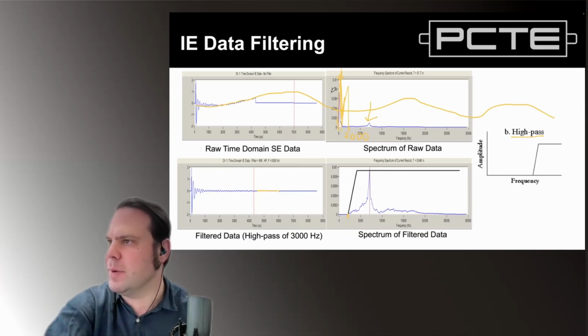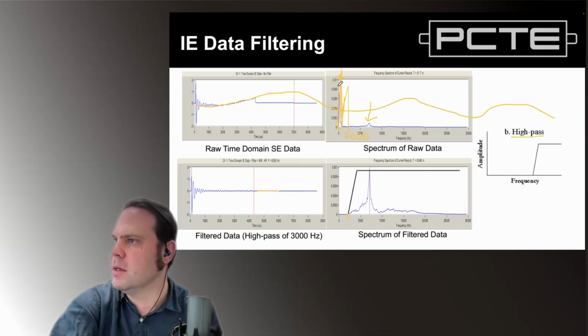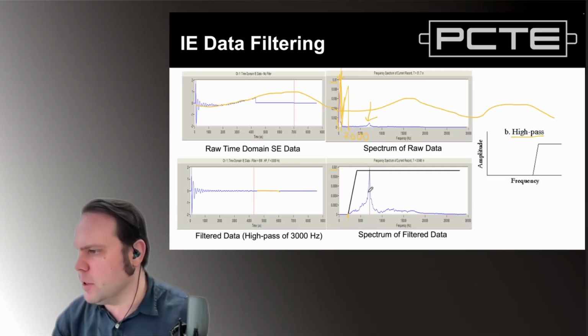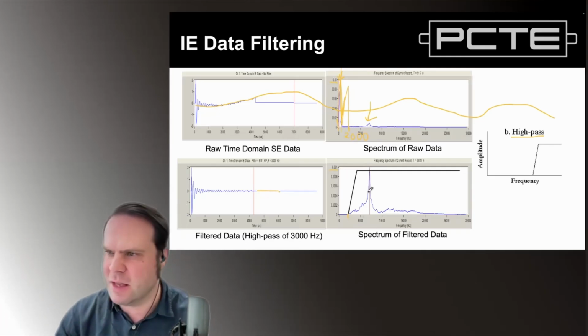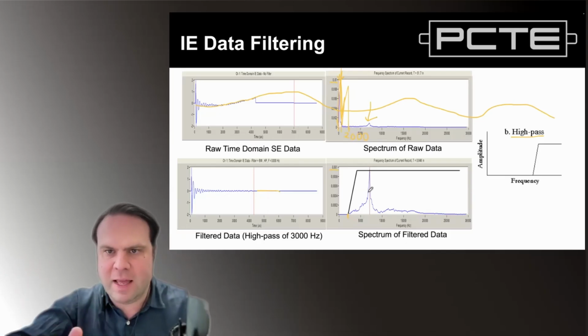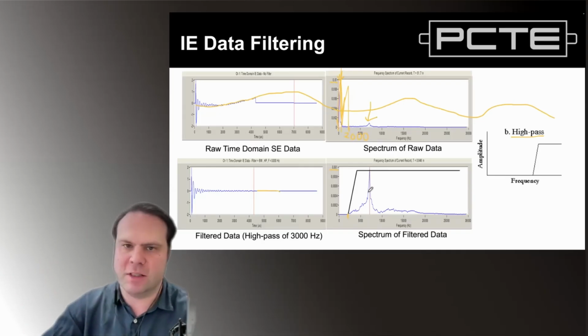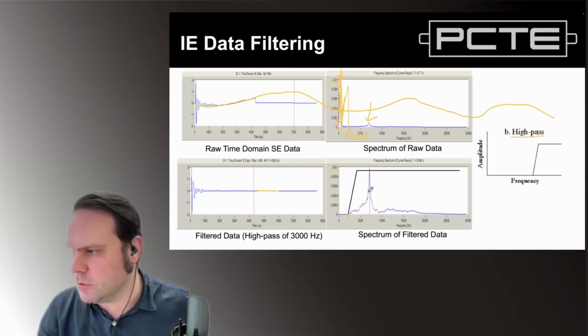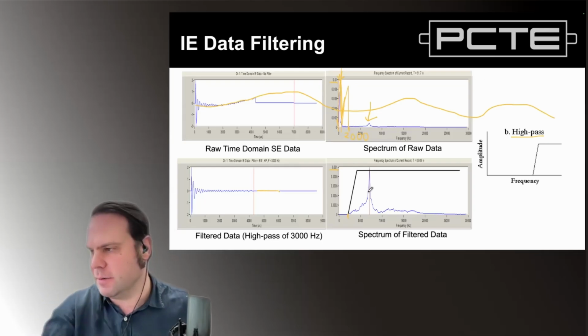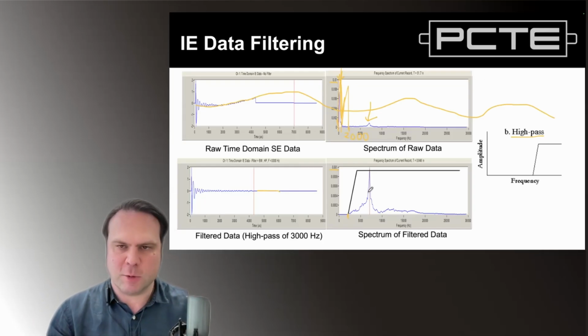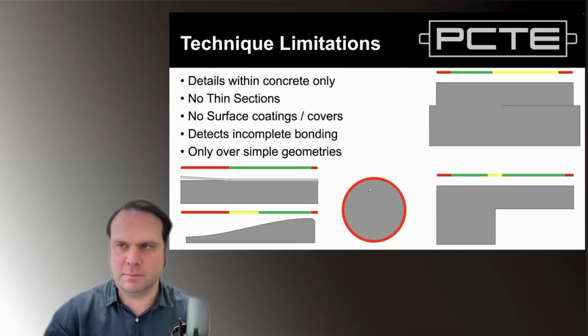And we can see this is an order of magnitude lower. 0.01 is the peak of this chart, and this is 0.001, but that is our result. That's our dominant frequency of about 8,000, 9,000 hertz, correctly captured because we've told it with a high pass filter to reject the frequencies below that 2,000, 3,000 hertz point and correctly provide us with a single dominant resonant frequency over the range of frequencies we care about to measure a thickness.